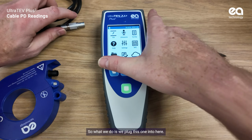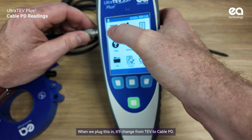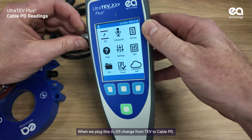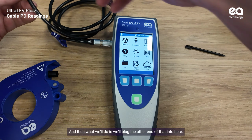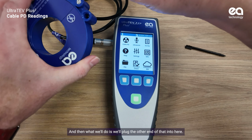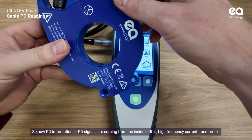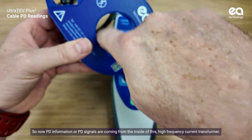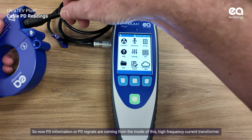So what we do is we plug this one into here. When we plug this in, it'll change from TEV to cable PD, as you can see there. And then what we'll do is we'll plug the other end of that into here. So now PD information or PD signals are coming from the inside of this high frequency current transformer.